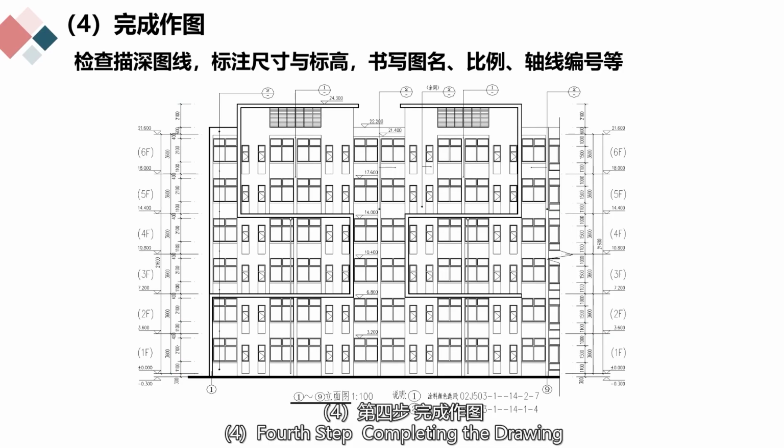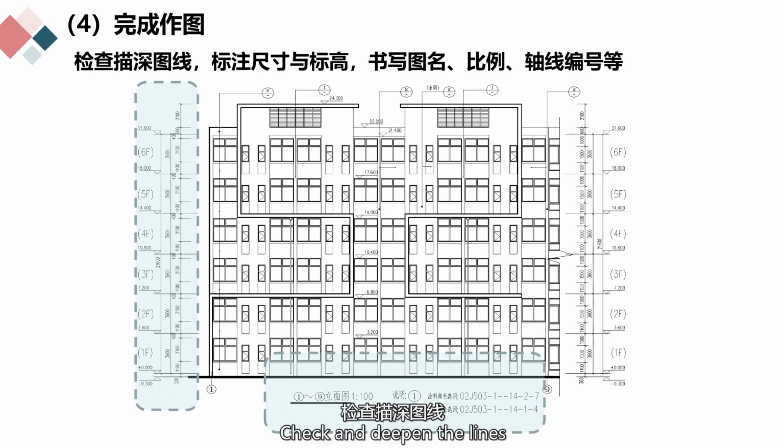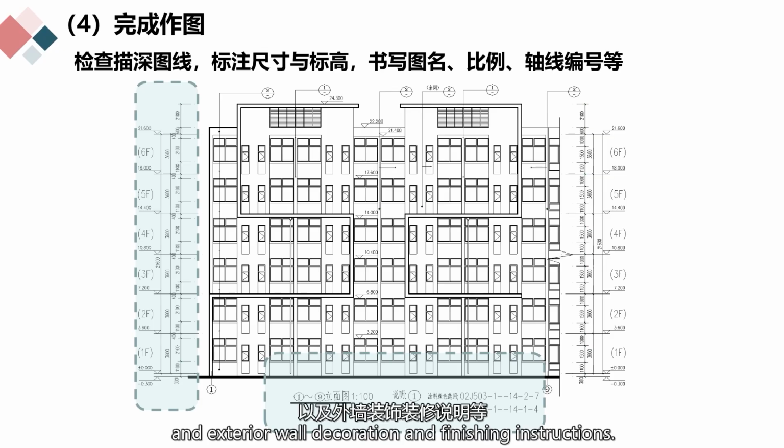Step 4. Completing the drawing. Check and deepen the lines. Label dimensions and elevations. Write the drawing name, scale, axis numbers, and exterior wall decoration and finishing instructions.